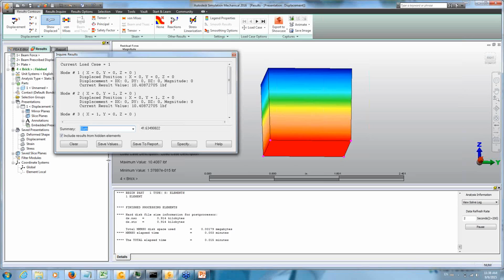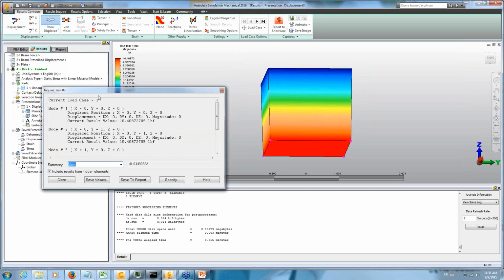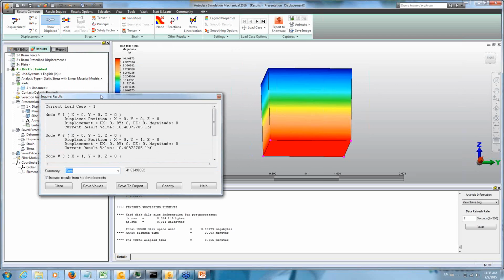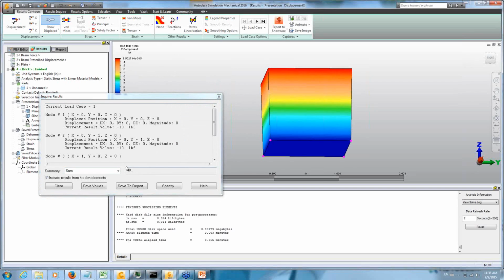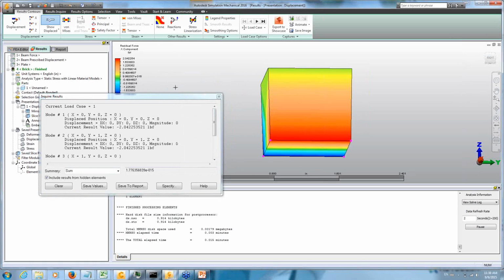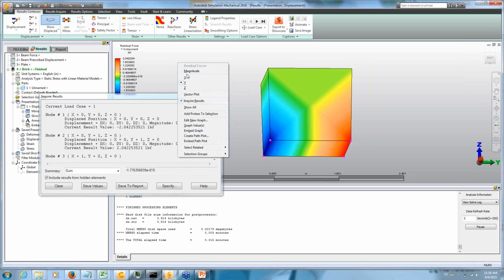And that's because I'm looking at the magnitude here. My forces are applied in the z direction, and they will generate some reactions in the x and y, not only in the z. So really, if I want to see my 40 pounds that I applied, I need to be looking not at the magnitude, but rather at the z, and that's exactly 40. And if I look at the x, that's basically 0, and at the y, that's also basically 0. Then you come back and say, well, if they're 0, why did they change my magnitude?